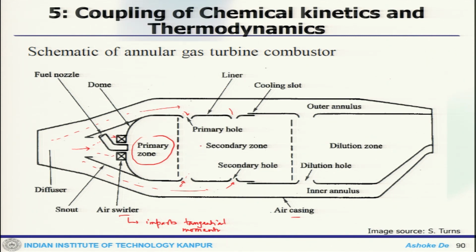So, whatever comes out from this side will also react with the excess air. There are two purposes of having the secondary injection. It will not only allow some reaction to take place if there is some excess fuel. That would be burned here, because now you inject some more air to it. Secondly, it will also mix with the hot product and smooth out the temperature profile a little bit, so that when it goes out, and that is also done through other dilution holes.